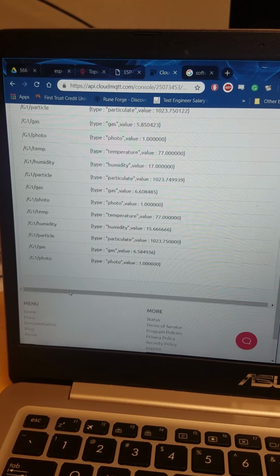And there you go. All right, this is for the serial connection part of our project. So you start by typing log on, and then it asks for the password, which in this case is just password. And it'll encrypt it and check it against the password that's stored in non-volatile storage. In this case, we got it correct. Then the little $ sign will show up showing that our shell is ready for user commands.